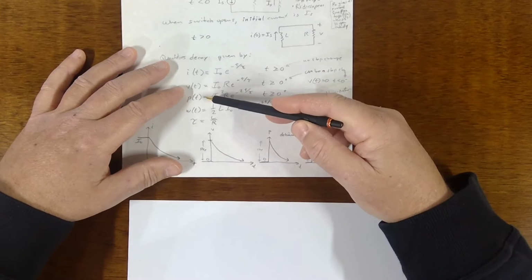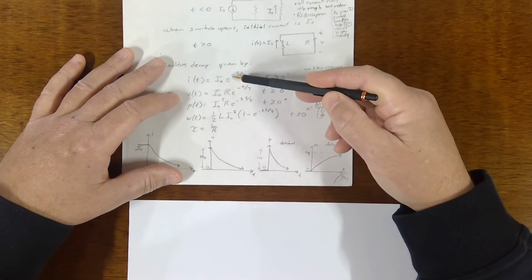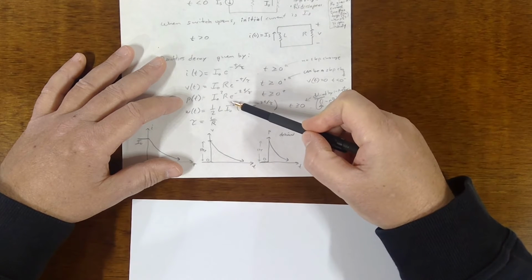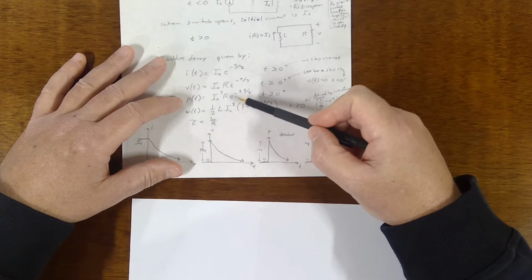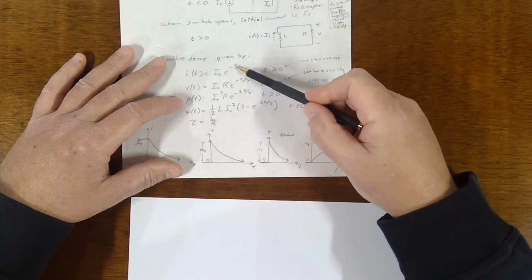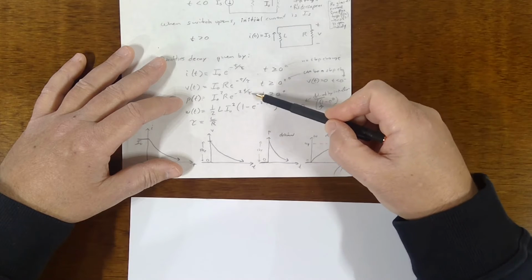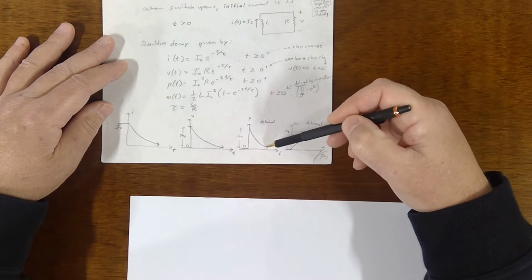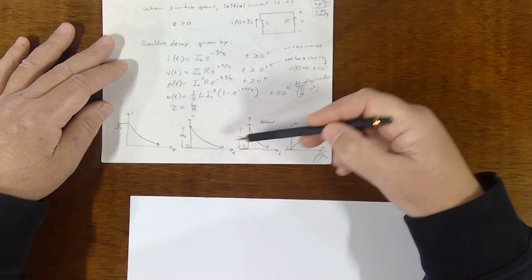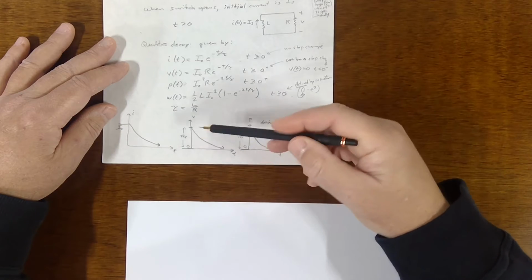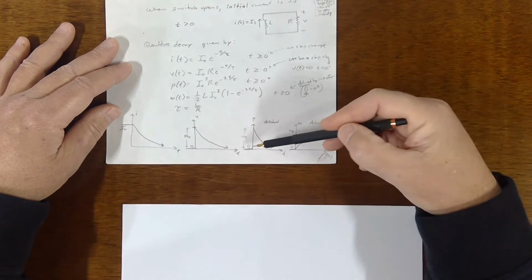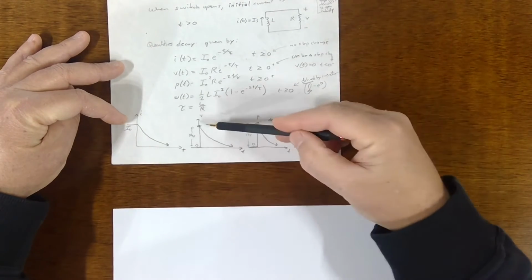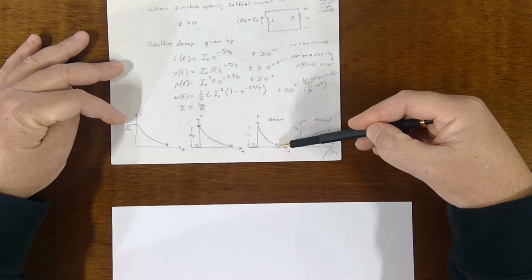Okay, P is just IV. P equals IV. So you multiply these two expressions together, and you get this I sub 0 squared R e to the, you'll add the exponents, e to the minus 2t by tau. So the power will decay faster, and it'll have a step response because voltage is initially 0. So 0 times any I will be 0. The initial power will be V times I, and then it'll decay twice as fast.